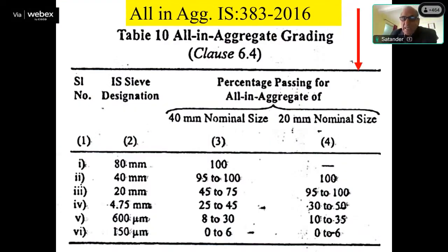For grading also, in bridges, most of the specifications say go as per IS 383. However, in the case of concrete road, or flexible pavement also, slightly different specifications are given as compared to IS 383. So please refer to the respective ones. If suppose an individual aggregate is failing in 10 mm, 20 mm, something, the combined grading is most important. Here one thing more to learn.